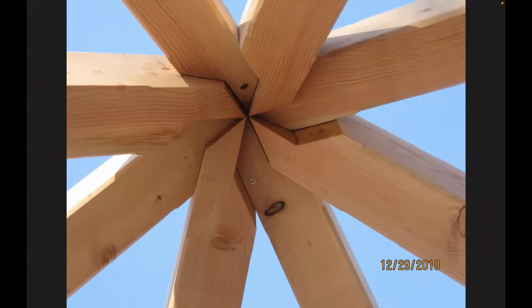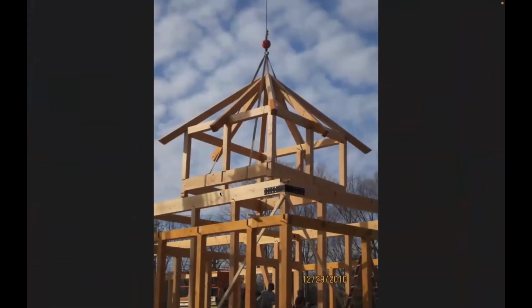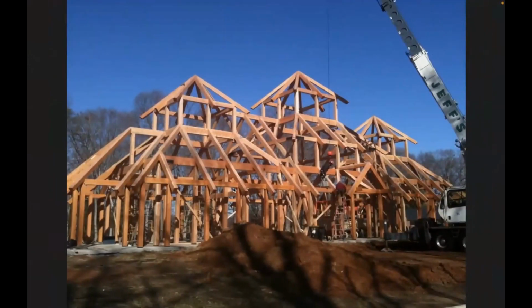All right, wonderful. So yeah, it sure was a lot of fun to do. David, maybe you can flip back one slide, like a longer shot. So you can kind of see, yeah, actually that was perfect. So we actually assembled the upper cupolas on the ground, and then the lower hip rafter, you see that has kind of an overhang. We set each of those hip rafters individually, and then we're able to tether it down on the rafter tail outside and just hold it into position. So once all four hips were just sort of floating out there, we lowered the whole cupola down and nestled it into those hips.